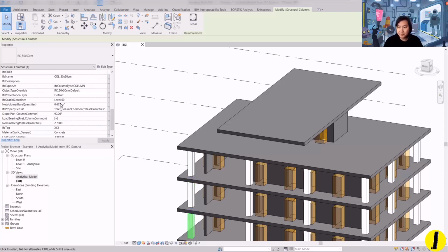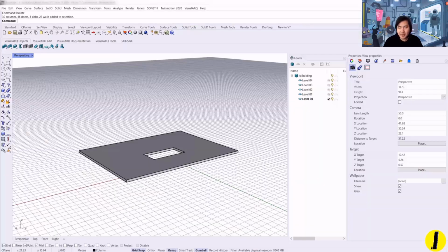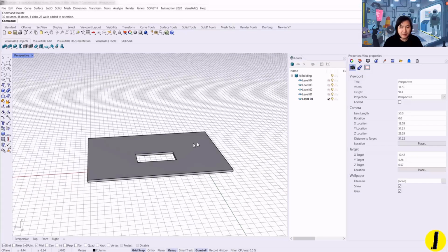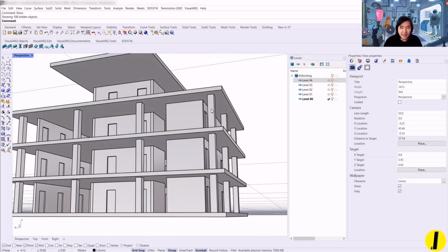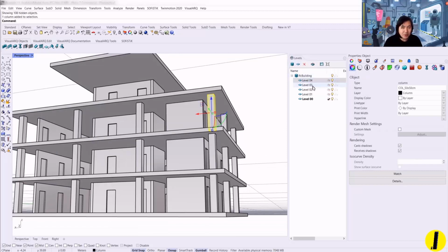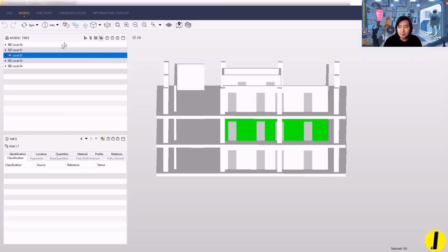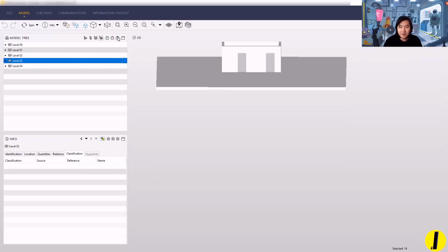This comes from the IFC building story and class, the class name. So you can see we have this building story structure in any IFC BIM software, and these elements belong to each building story. That's how we can tell in Solibri, for example, which story these elements belong to.